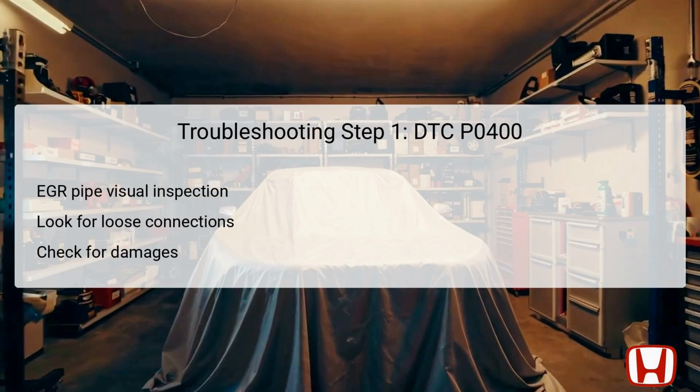Starting the troubleshooting process involves a comprehensive visual inspection of the EGR pipe. Technicians should check for any visible signs of looseness or damage. It's important to inspect the connections where the pipe meets the EGR valve and exhaust manifold for any misalignment that could lead to leaks. If the EGR pipe appears to be intact and secure, the technician should move on to the next steps in the troubleshooting process.